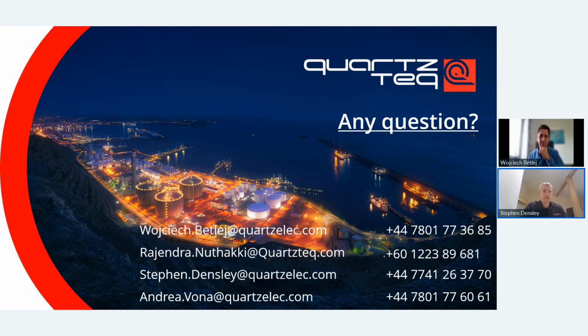Thank you. Okay, two more related questions. One is, on the PD trend, we show three different trend curves. Can you explain what they are? Right. You see three trends because we always measure partial discharge on every phase. That's why you have seen phase A, B, and C, or whatever you call your phases. So you will have three separate lines trending over time, and they simply measure three phases simultaneously.